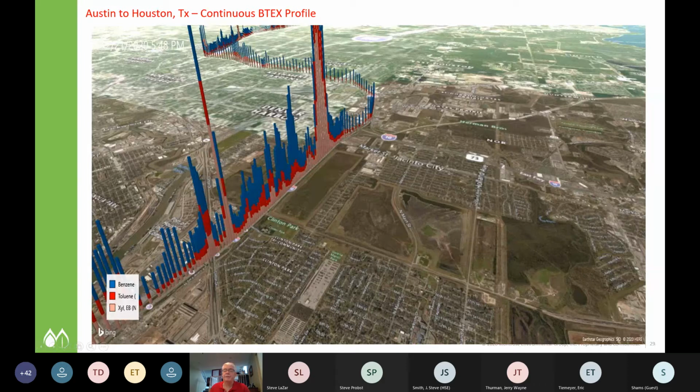Now, if we really wanted to pinpoint exactly where this was coming from, we wouldn't be doing it at 65 miles an hour down the highway. We'd stop and set up a grid pattern, and we would chase a plume basically until we found it. We'd sit there and monitor and accumulate data, just like we did with the stationary sensors, to build into the model for the triangulation.